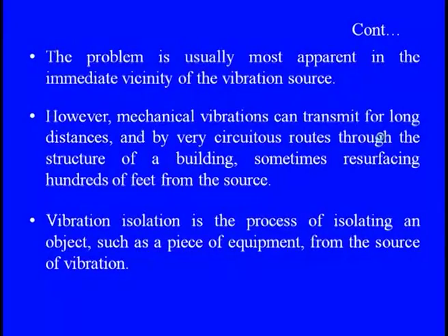Because they are rigidly mounted on the floor or wall, these vibrations transmit rapidly through these solid surfaces. The problem is usually most apparent in the immediate vicinity of the vibration source, and we need to apply the concept of vibration isolation on these sources straightaway.